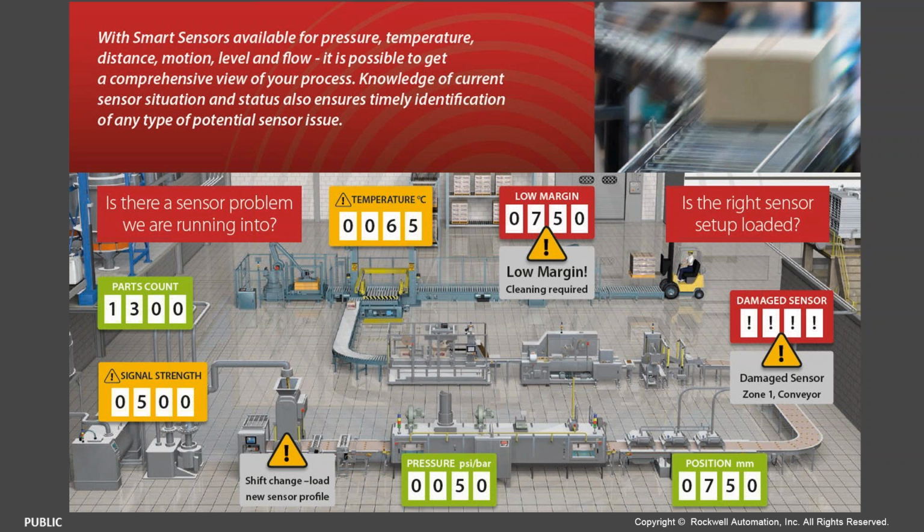Some sensors require different configurations depending on what is being produced. For example, the registration mark sensors used in packaging and labeling machinery typically need to be retaught every time the label or the web material is changed in order to detect the new color combination. What this means is that every time a label or web is changed, someone who knows how to teach the sensor has to physically go to the sensor and manually teach it.